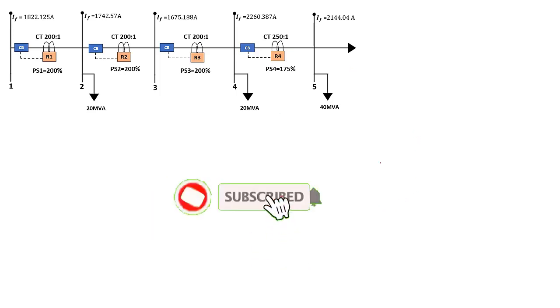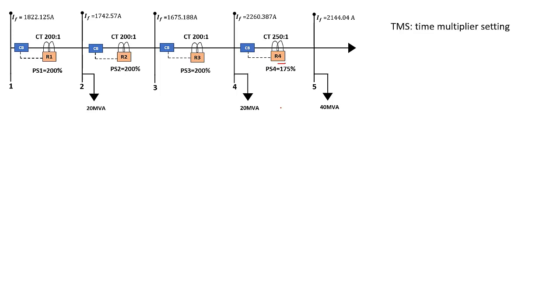Okay, so in this tutorial, we're going to focus, as I said earlier, on calculating the tripping time of these IDMT relays. Now, there are important terms that one must take note of when calculating the IDMT relay tripping times. Those terms are the TMS, that's the time multiplier settings.